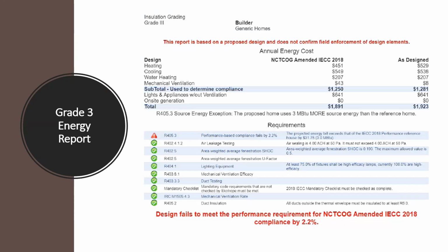So when you go in and look at a house and it's insulated but poorly insulated, technically that's not going to even pass code. That's not passing base code. That's not passing the energy model. And if it isn't reconfirmed through the energy modeler and determined that grade 2 or grade 3 is acceptable, then technically it should be red tagged on site and forced to be compliant with the code. I know it's a gray area.